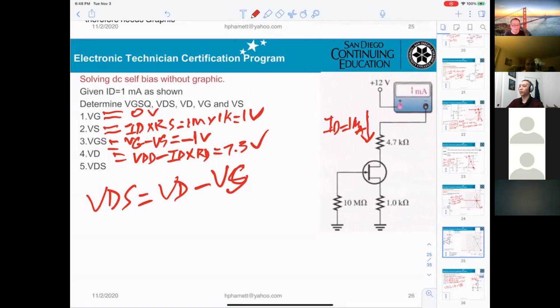You must understand first. Then we can talk about how to fix the problem. When you troubleshoot, you have to measure from one point to another to see what voltage you want or don't want.